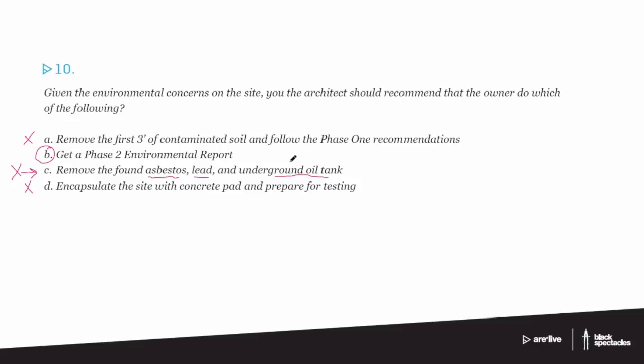Often, when you do a phase 1, they'll go through the history of the site, they'll go through the photographs, the aerial photographs, and they'll say, we don't really need to worry about it. It doesn't look like there's anything. I wouldn't worry about it unless some specific information comes. At which point, you can go ahead and recommend, phase 1 doesn't say that we need a phase 2. I recommend we move forward with our design.